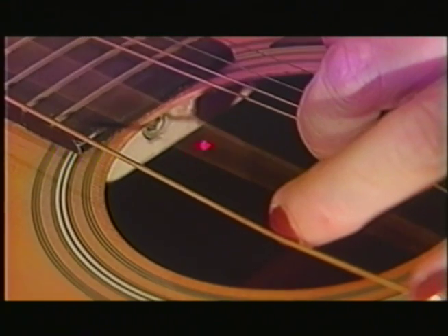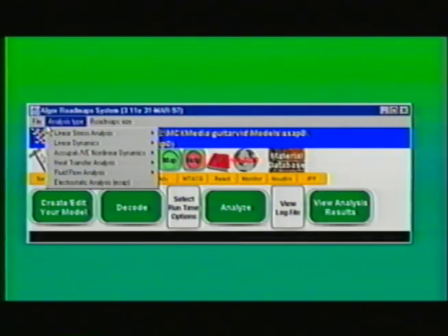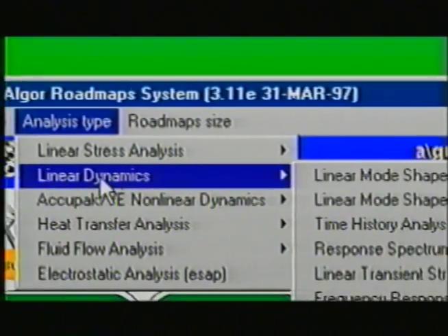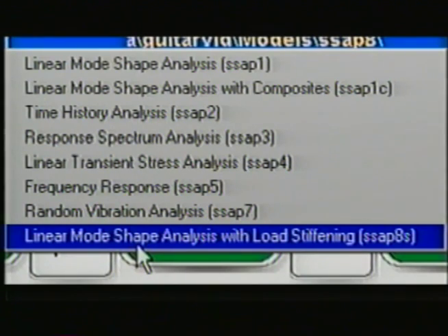In an airplane or car, loads or forces, and therefore natural frequencies are constantly changing. Therefore, to predict the dynamic response, you must consider load stiffening. ALGOR offers 2 ways to predict frequencies as a result of load stiffening. The first way is with the vibration level 2 extender.